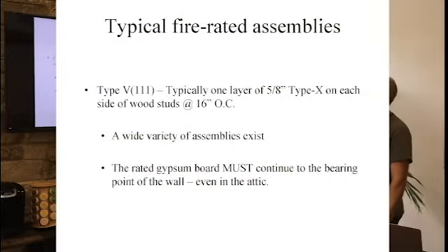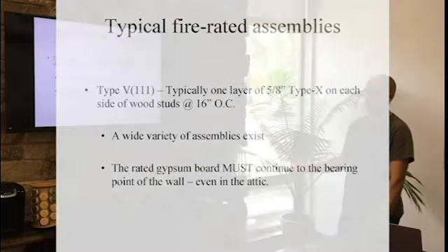And we've gone over some of these before. What are some of the typical fire rated assemblies? For 1 hour walls, in 1 hour rated bearing walls in a wood structure, 1 layer of Type X 5/8 inch thick gypsum board.